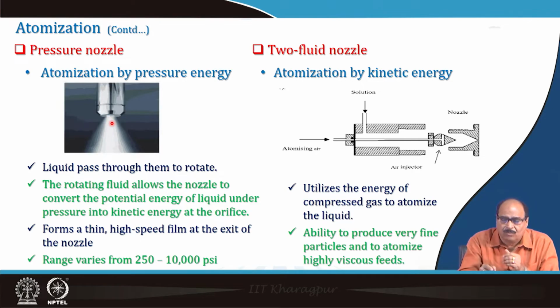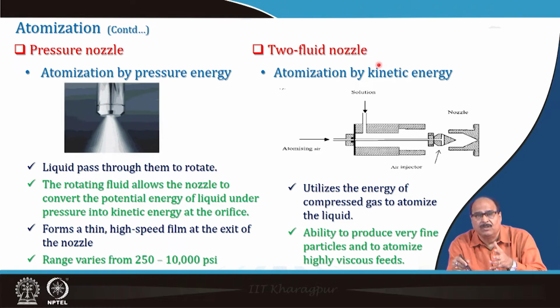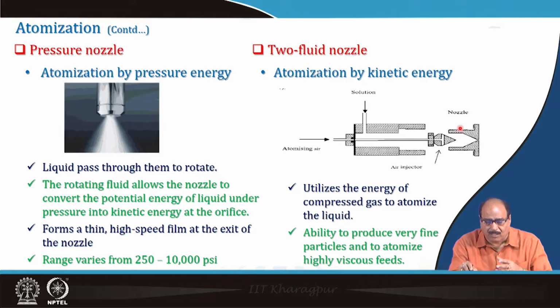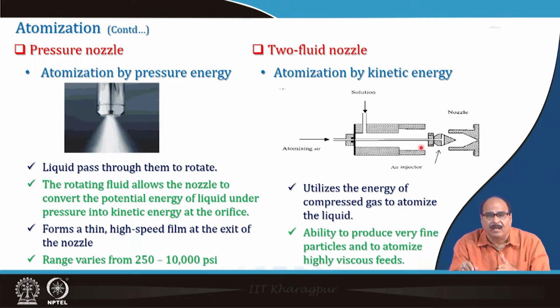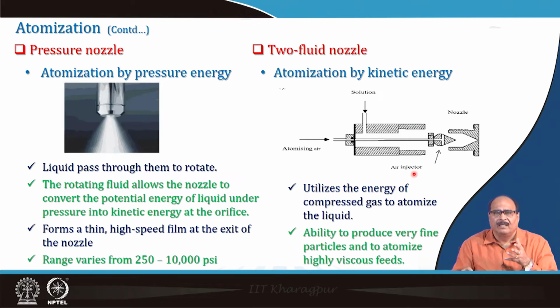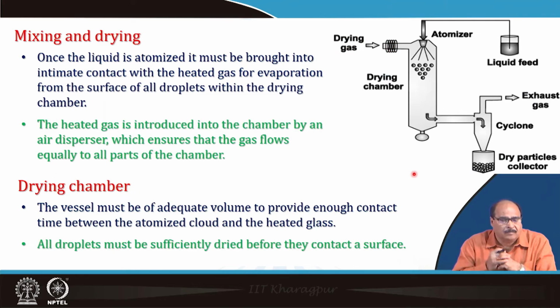Okay. Then the two fluid nozzle system, where basically the principle is atomization by kinetic energy. You can see here in the schematic figure, it utilizes the energy of the compressed gas to atomize the liquid and has the ability to produce very fine particles and to atomize highly viscous fluid. That is, if this is a thick paste, concentrate etc., they can also be suitably atomized using two fluid nozzles.